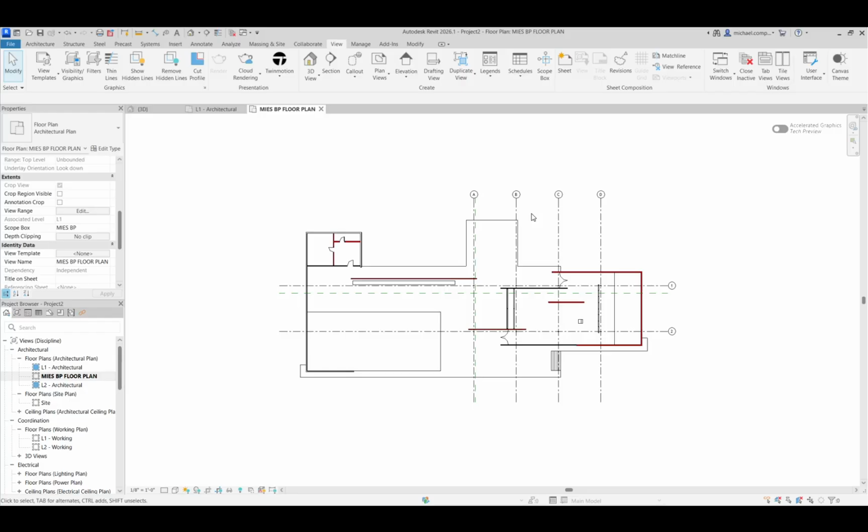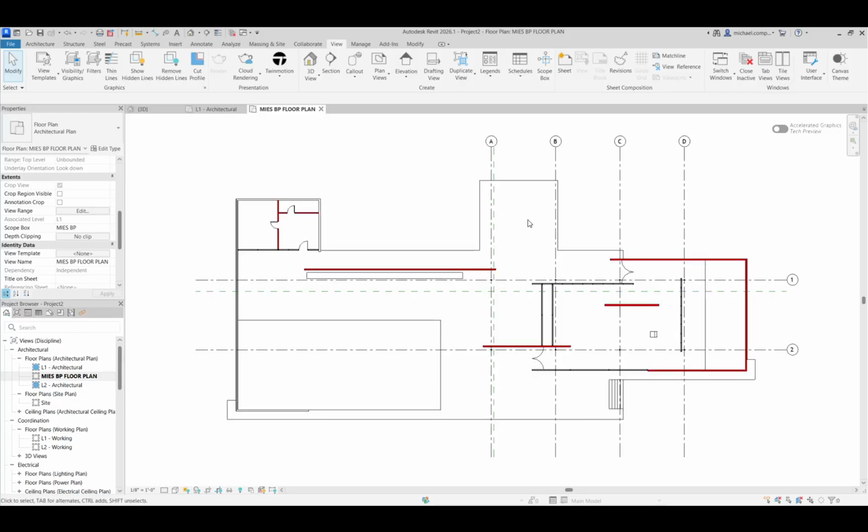The next thing I want to show you how to do is to put back the graphics that aren't necessarily important for this image. And in this case, the grid lines are super bold, and they're getting, at least for me, they're confusing the line work of the architecture. So what I'm going to show you is how to select all the lines with just one click and gray tone or half tone them.